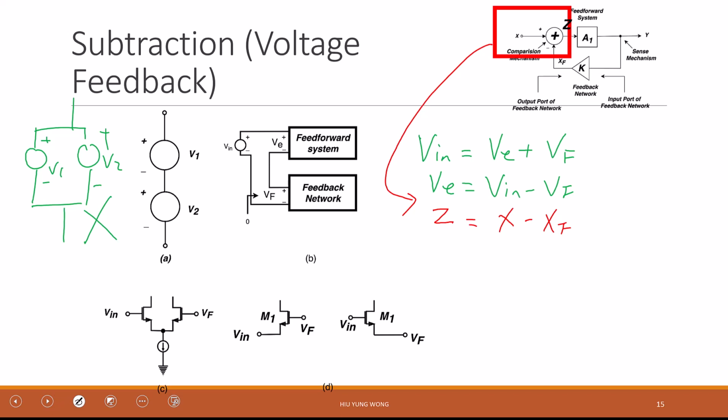But let's not. I want to say what V out is related to the input. You're all right. This one I give you GMN instead of RD because I'm talking about single-ended. Okay, so this is the equation. So I'm not testing your gain. But what is the right-hand side? What times what equals V out? This is single-ended. I should have said that it's single-ended. What times GMN parallel RP equals V out?